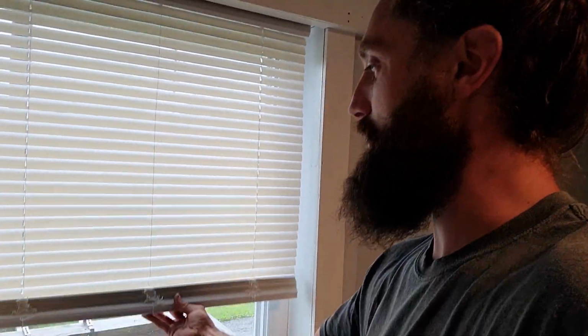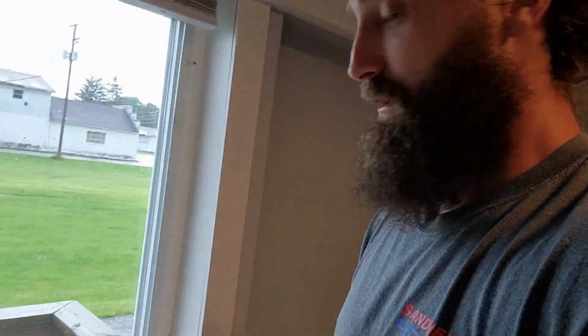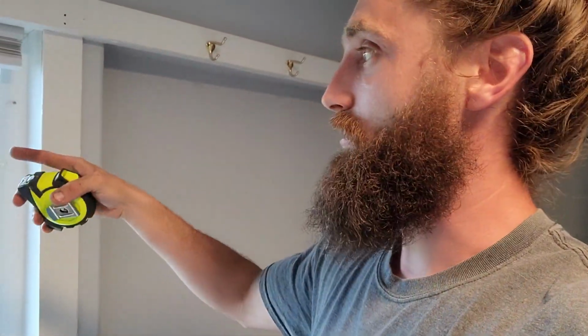So you can see here, this is what we're actually considering our master bedroom. It's the larger of the two. And what I opted to do, because these rooms are pretty small, I needed to have egress windows, I opted to put casement windows in to meet the egress requirements of these rooms.